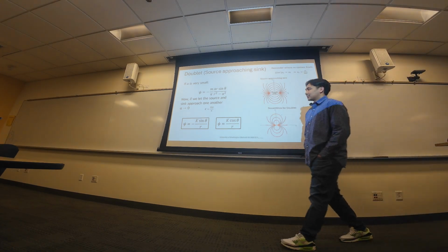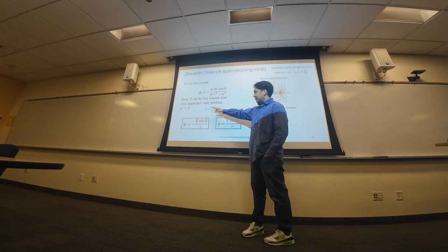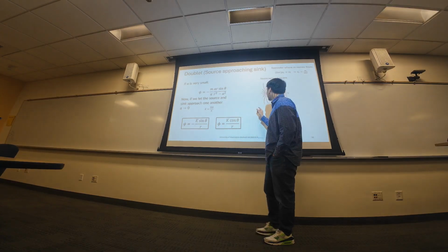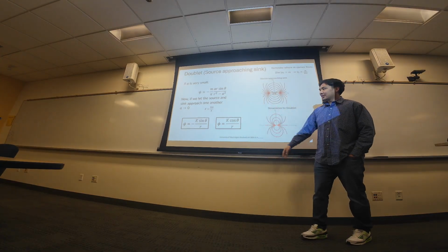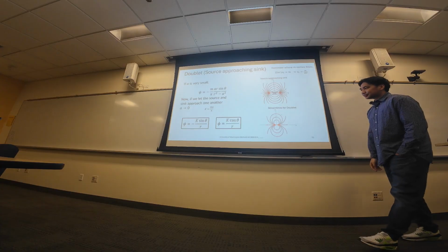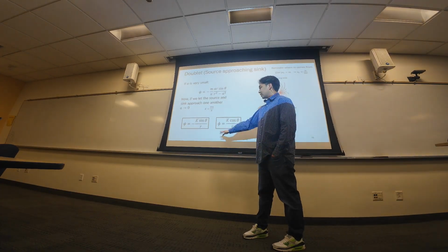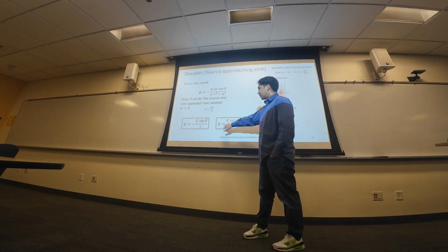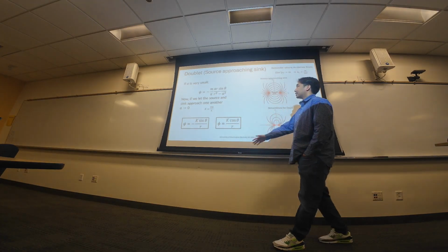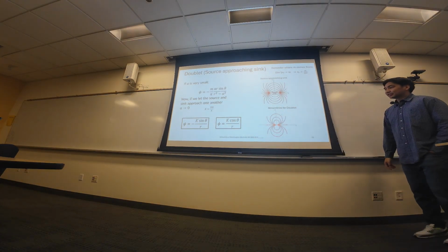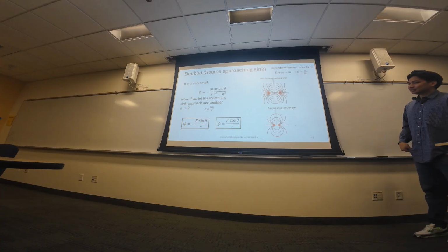So this M was defined earlier. It's not mass, it's that flow property. A is the radial distance between these two from the center, and pi is pi. And these are now your equations for your stream function and velocity potential for a doublet with that K constant.